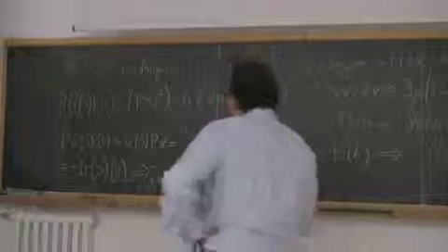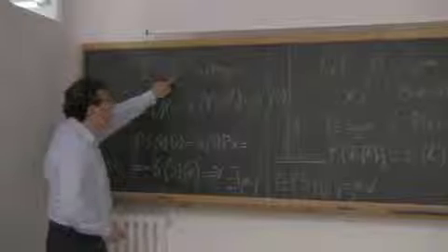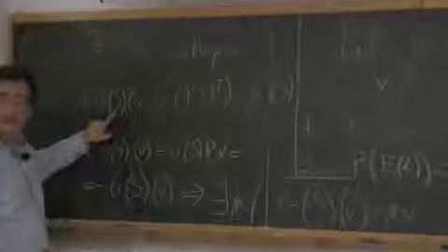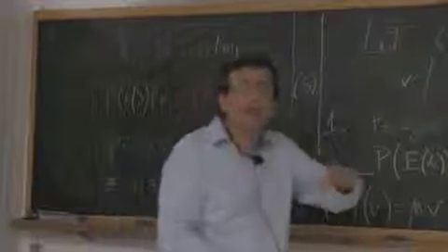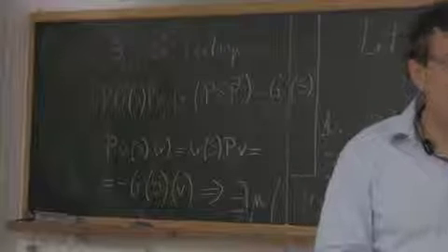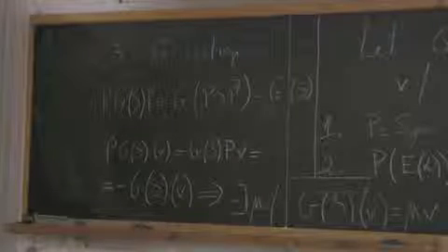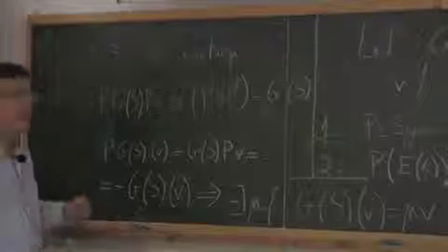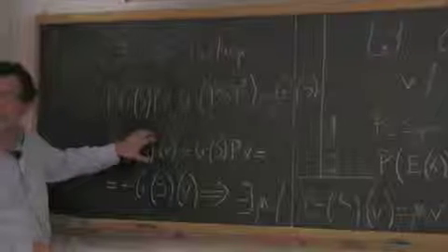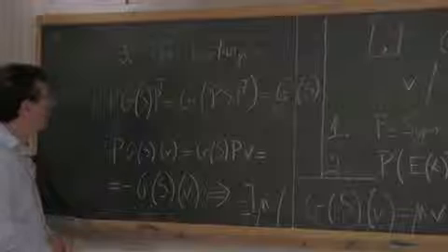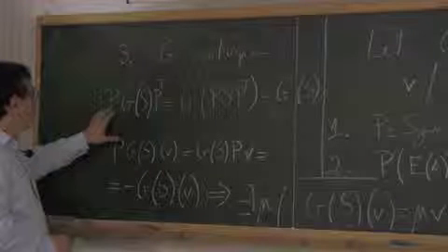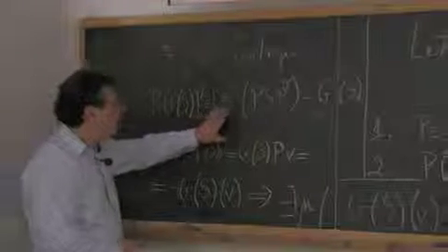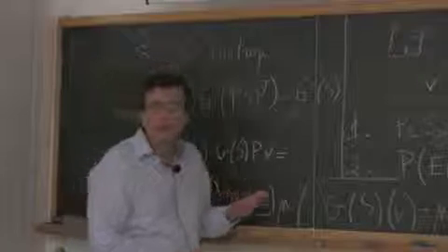So, you have a function G which is mapping a symmetric tensor S into another symmetric tensor. To be isotropic means that for every Q orthogonal, Q G(S) Q transposed is equal to G(Q S Q transposed).